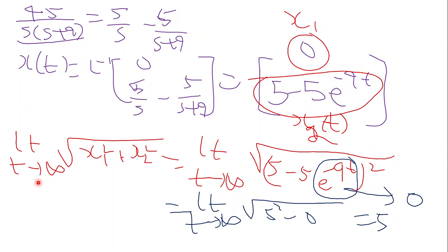One is to find L inverse of (sI minus A) inverse. From that find x of t equal to L inverse of (sI minus A) inverse into x of 0 plus L inverse of C (sI minus A) inverse B U of s. Second, y is equal to Cx. Cx means if you have two elements, one element you multiply by x1 of t, then the second element in the C matrix you multiply by x2 of t. Then depending upon the question asked, you have to answer.